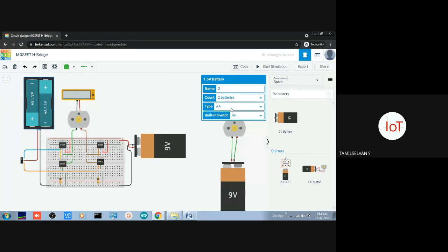So if I give 2 or 3 volts, it would be better to operate my PMOS device, because it is dropping 2 volts internally. Okay, so if I give above 2 volts only, it will work perfectly. So I'm controlling this PMOS and NMOS with the help of at least 3 volts. Okay, above 3 volts also you can give.